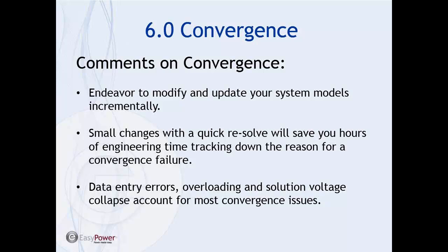So, like I just said, endeavor, please, to modify and update your system models incrementally, especially if they are large. Please, if you want to save yourself a lot of time, make small changes and then do quick resolves in Powerflow to make sure that you don't create a convergence failure. You can very quickly back up and track down where the problem is if you make incremental changes.